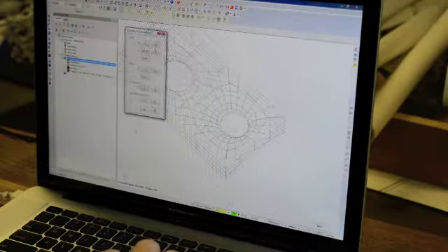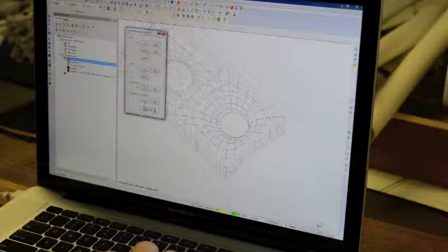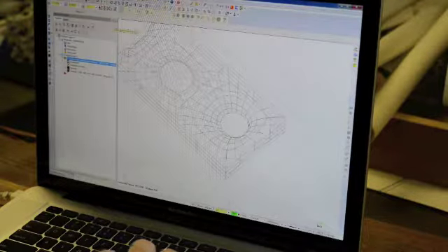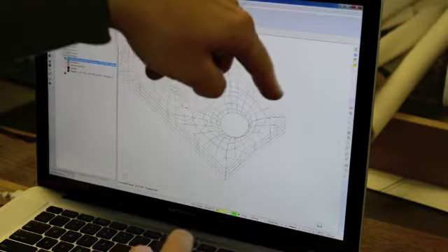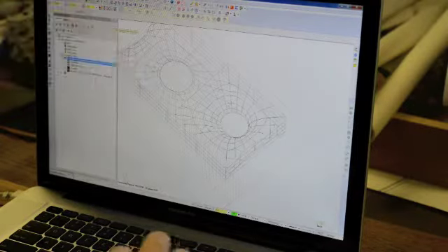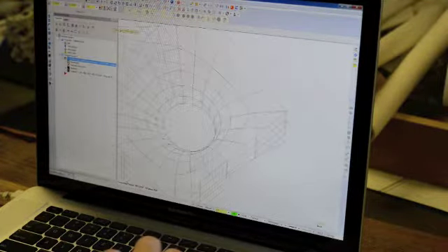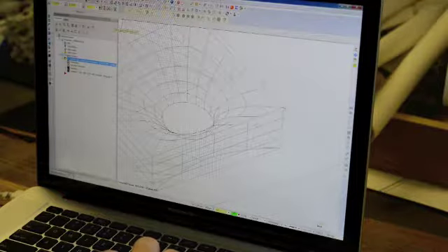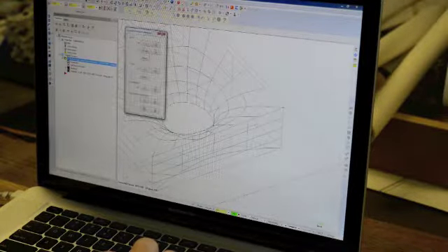So you press OK, and then it wants a start point, and this is where the spindle will actually come down and start doing work. So it can be, again, selecting up top there, press OK.